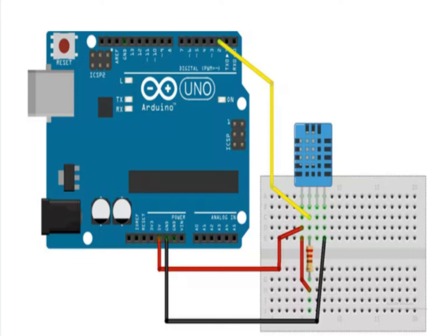Your DHT sensor may have only 3 pins. In that case, check the labelings on the sensor and connect ground on Arduino to ground on the sensor, 5-volt on Arduino to VCC of the sensor, and pin 2 of Arduino to the remaining pin of the sensor. You will be all good.